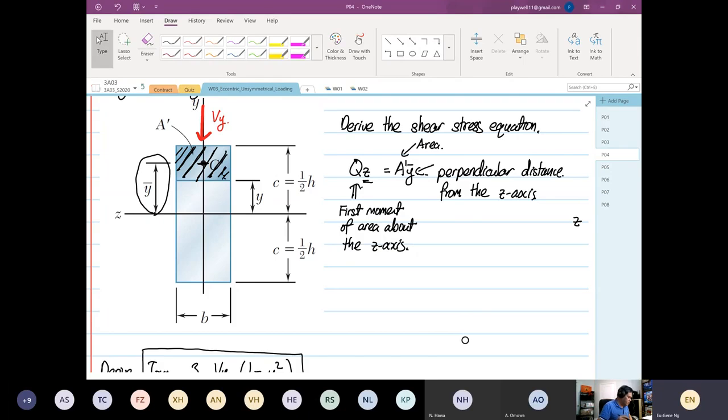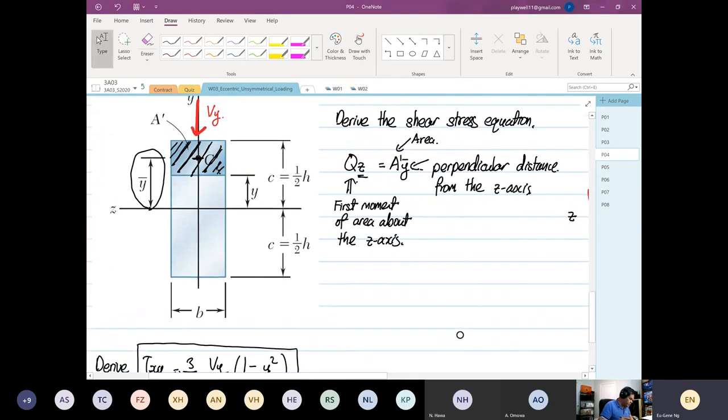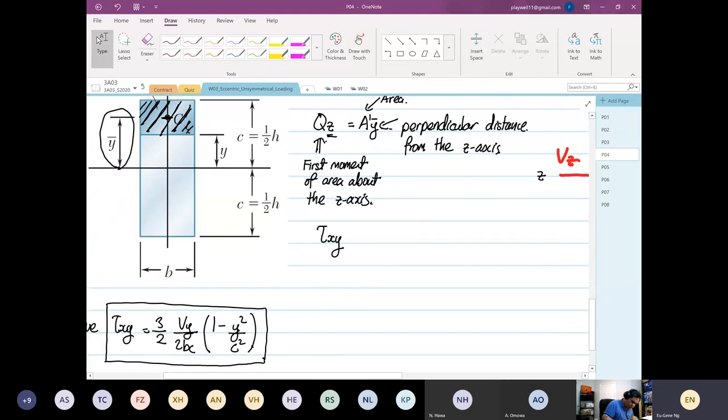On this diagram over here, on the left hand side, the shear now is on the x plane, y direction. Right, because the plane that we have now is the plane intersecting the x-axis, and the shear stress or the shear force is acting in the y direction. So this is equal to shear yx, which will be equal to Vy over Izz, Qz multiplied by thickness.